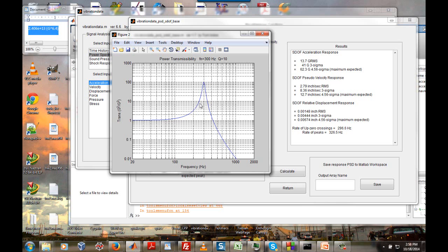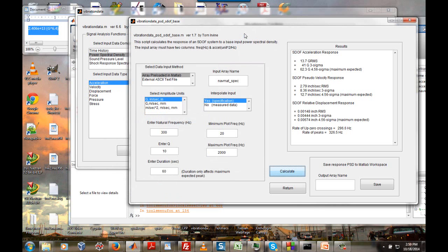And sort of the bottom line, the quick story is if this were measured data and we were trying to pick off the Q value, we would not say, okay, let's just go over here, pick off Q squared. Instead, it's much better, more robust and all that to use the half power bandwidth or 3 dB bandwidth method, which we've done before. And I'm not going to repeat that, but we've done that in class before. So for experimental data, please use the half power bandwidth method.